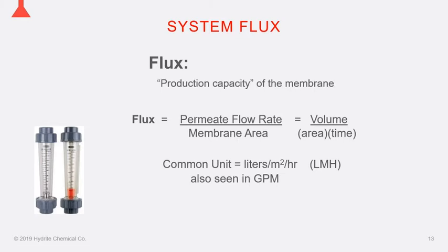But why is flux important? If you want to compare different stages or loops of a membrane system, different stages could have different membrane spacer sizes, and they could have different membrane area. So if you want to get an idea how one bank or loop of membranes is performing against another to see if maybe one is cleaner or dirtier than another, you could use the actual flux reading that compensates for the variance in area between two different membrane loops or stages. Little technical term, but hey, let's raise the bar and get a little more education into you.